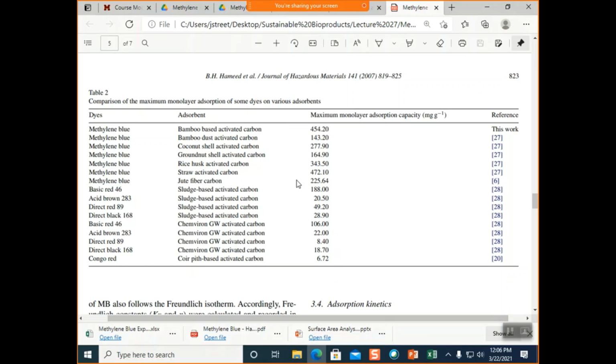And then you saw how much they used. It's not very much. You're talking about milligrams per liter. That 5 kilos would probably last you for 30 years if you were just doing it off and on. So it's a good way, in my opinion, to do an initial check. Or if you're just concerned about how well your adsorbate will work to absorb liquids, then it's a good method to use, and it's very publishable. This data is very publishable to try to determine how well yours works versus somebody else's.